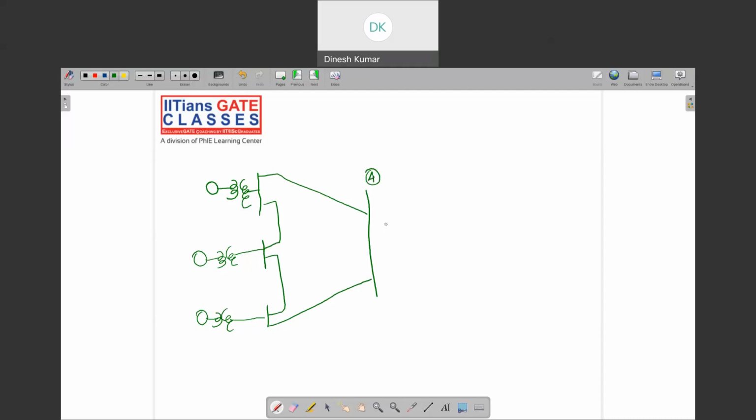Okay, so this is the first bus, second bus, third bus, and this is the fourth bus. We can consider one of the buses the reference bus, or a slack bus. We can consider any one as reference. Assume that we are grounded, because everywhere there is a source, right? So we can just ground this. This will be the reference bus 0, or we can give some angle 0 as the reference bus. It depends on the problem.